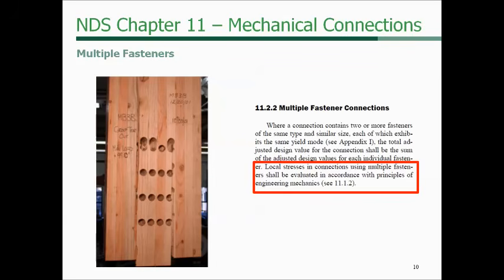And there's one more clarification related to the outer rows that I wanted to mention. I think it was mentioned that 5 inches, but for glulam timbers, it's actually 10 inches. Yeah, that's great. I probably mentioned that very briefly in passing, that that is a new provision in the NDS.